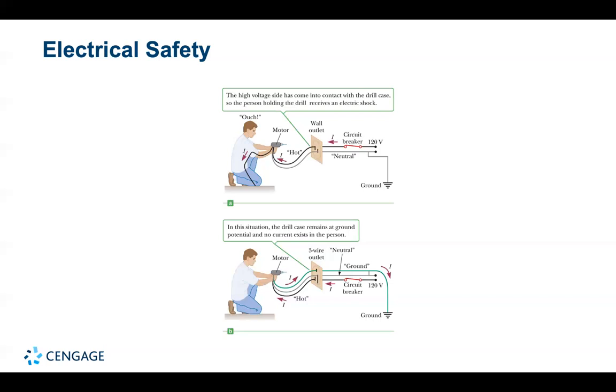Electric shock can result in fatal burns or cause the muscles of vital organs, such as the heart, to malfunction. The damage to the body depends on the magnitude of the current, the length of time it acts, and the part of the body through which it passes. Currents of 5 milliamps or less can cause a sensation of shock, but ordinarily do little or no damage. If the current is larger than about 10 milliamps, the hand muscles contract and the person may be unable to let go of the wire.